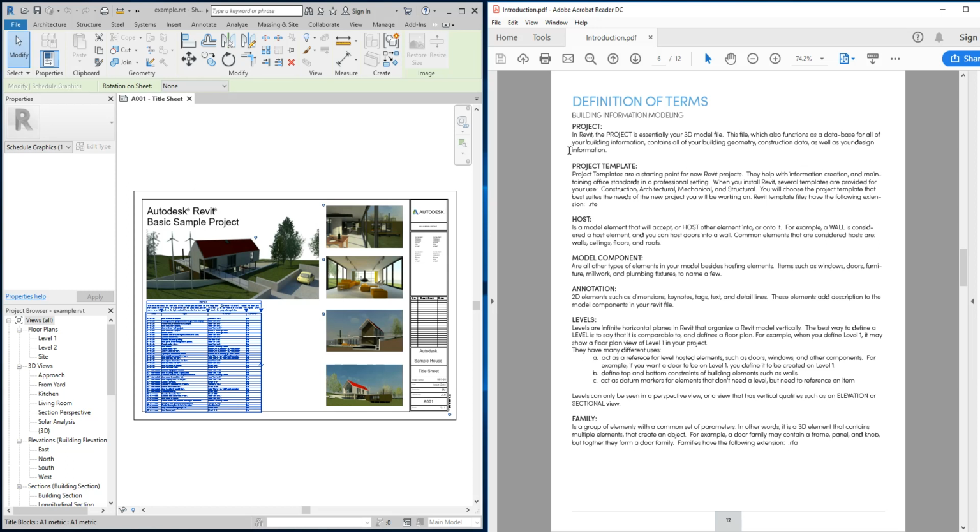All right, so in AutoCAD, we didn't have a template. When you first started using AutoCAD, it was a completely blank file. There was no definition in it, right? So AutoCAD, extremely generic. You go in, you create a template that you can then use to start working, right? And what that means is you define dimension styles, text styles, you define layers, you define pages, you define blocks. There's probably 10 different things that you predefine in your AutoCAD template so that when you go to work, everything is there available for you to start working with.